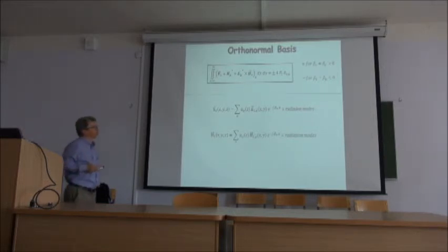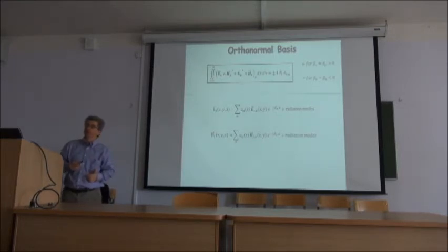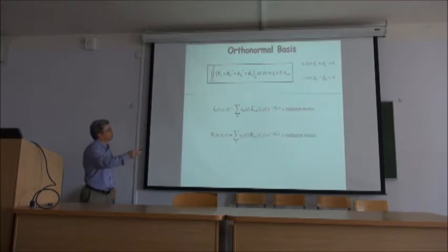So what we have here is that we have an orthogonal basis. So this allows us to have any field that is going inside this waveguide, we can propagate in terms of this base. So those modes actually form a base that can take an incoming field and I can decompose that. Then I can have that both for the electric and the magnetic.